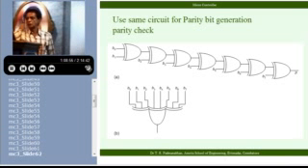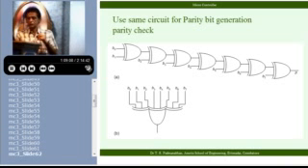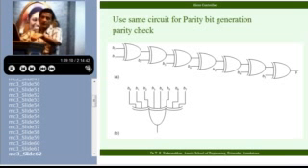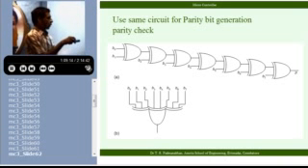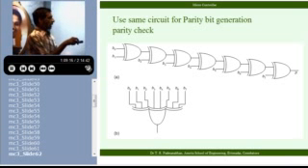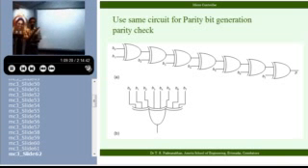See here, I have done a circuit for parity checking. You just check this and see whether you get it properly. I have done simply repeated exclusive operation and then got the output. You just see here, if B0 and B1 both are 1 or both are 0, I get a 0 here. That's a basic parity checking.